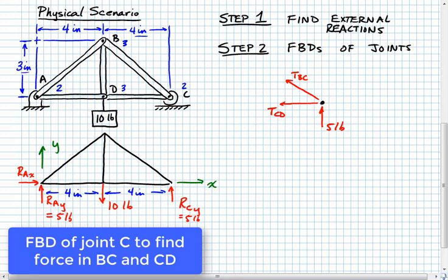Basically, what we need to do here is, I guess I need to talk a little bit as far as why we know the directions of those forces. Since in this truss we've met all of our requirements, we have our members only connected at 2 points each with frictionless pins, and so we already know the direction that happens as far as the force in those members. All right, and so that's good.